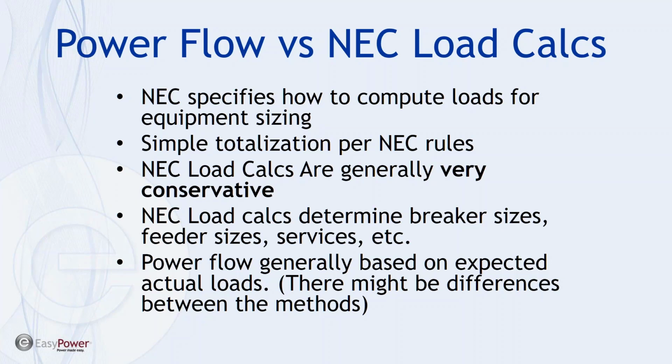So in terms of the power flow versus how the system was designed, there's a fair amount of conservative padding when you're looking at load calcs by the National Electric Code. You can recognize this when you talk to a utility company about what they provide generation-wise when you approach them with a specific design requirement for a new plant.